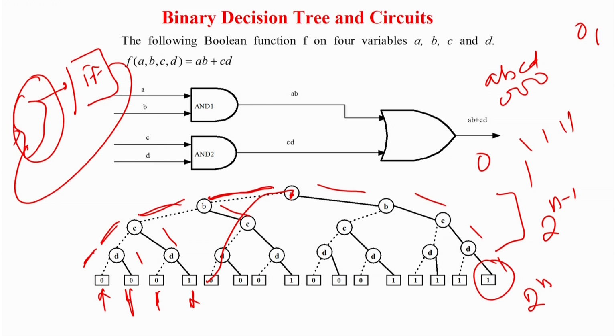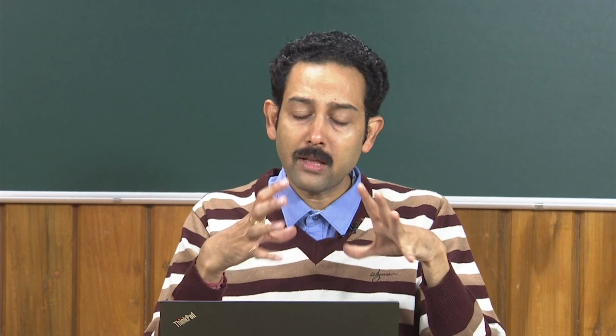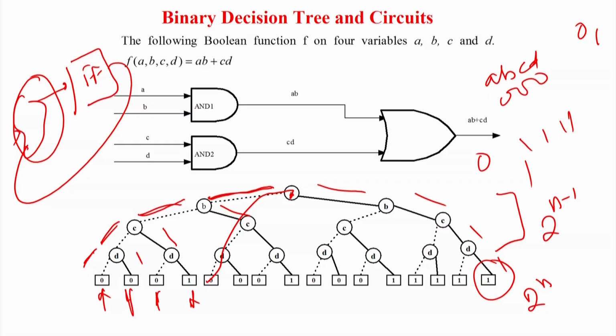We will have an explicit lecture to see how binary decision diagrams can be used to represent models, the state space model, which is the most difficult part in verification. So first we are trying to see how to model this NSF block, that is a combinational circuit, using some good data structure. Once we can model this, modeling the state variables is trivial, because flip flops just take the value from one state to the next state. This is just a straight transition.